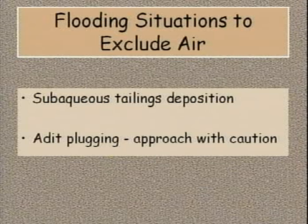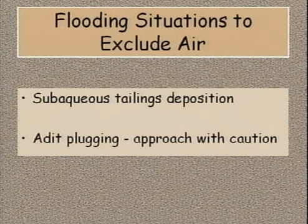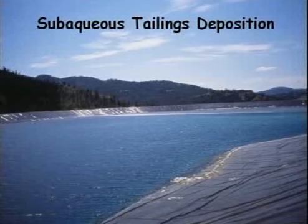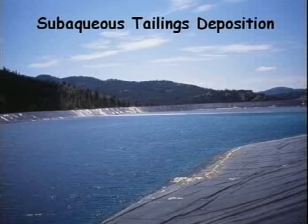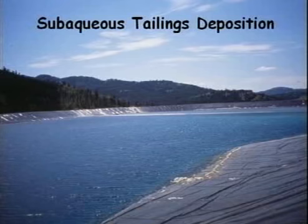There are 2 general mining situations that might work to implement such a flooding control measure: subaqueous tailings deposition and underground mine adit plugging. This flooding technique works well on tailings, which are often placed as a slurry anyway. However, submergence has to occur quickly after the waste is placed, ideally within a week to a month of the waste's generation. This timing prevents the generation of sulfur salts that upon submersion would produce ARD. These were talked about a lot this morning.